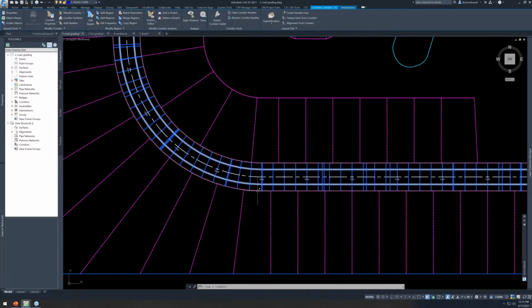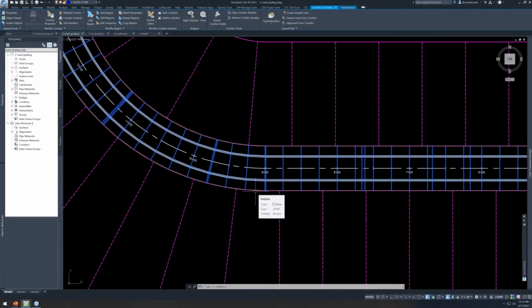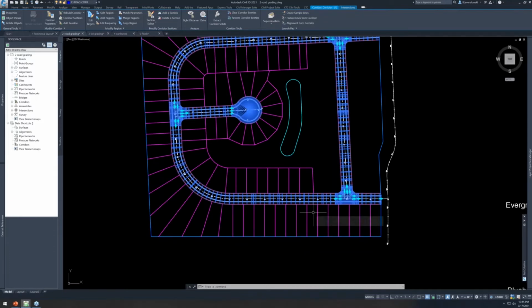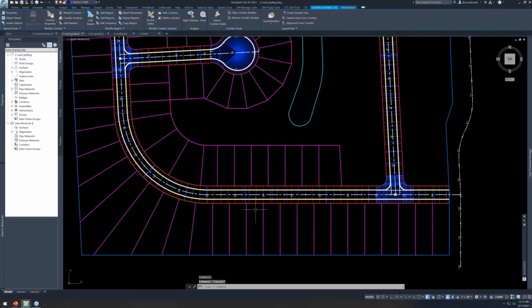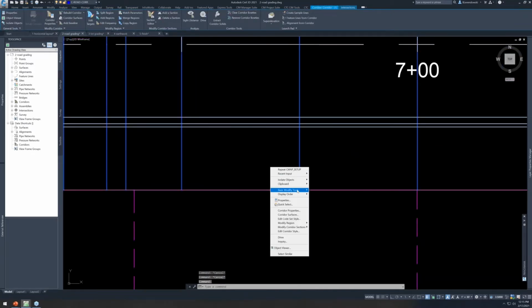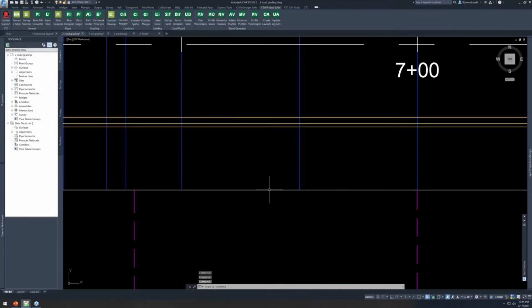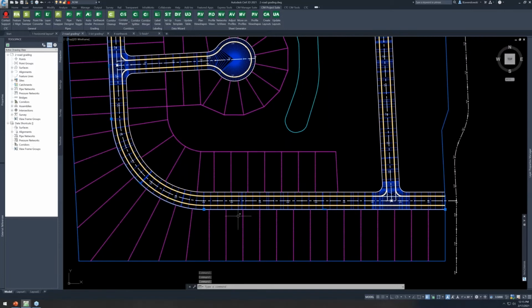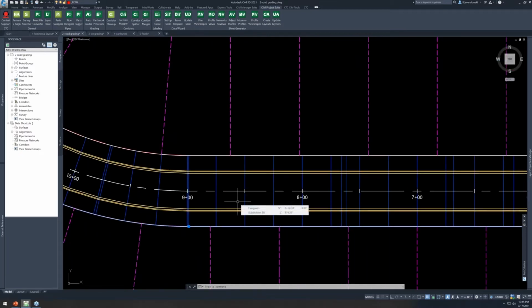Okay, so in this process I'm showing today, instead of extracting a dynamic feature line, and while it might work for some of you in some projects, if you get a project that's looping all over the place and left and right kind of varies across different corridors, you're going to find it easier to instead just use your right-of-way geometry that you drew in your horizontal stage and create a feature line from that and simply pull elevations from the corridor surface. Okay.